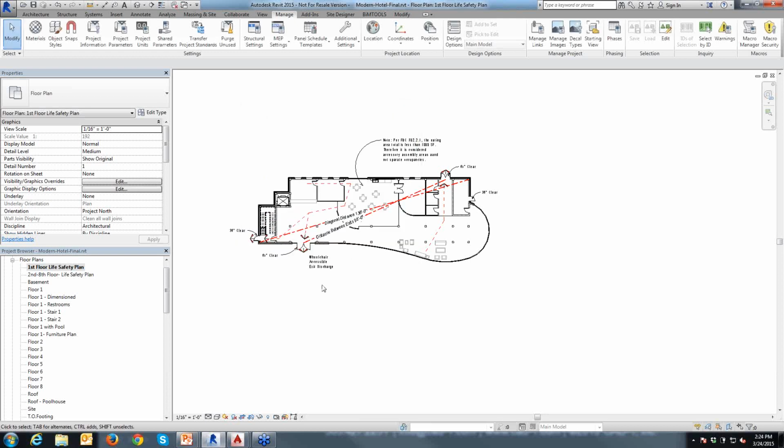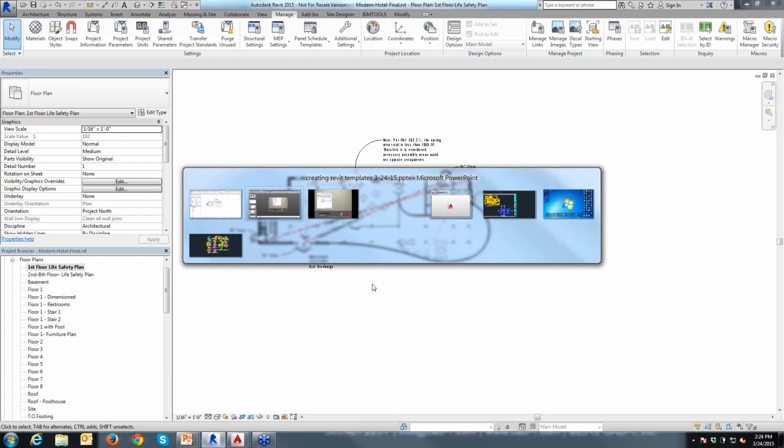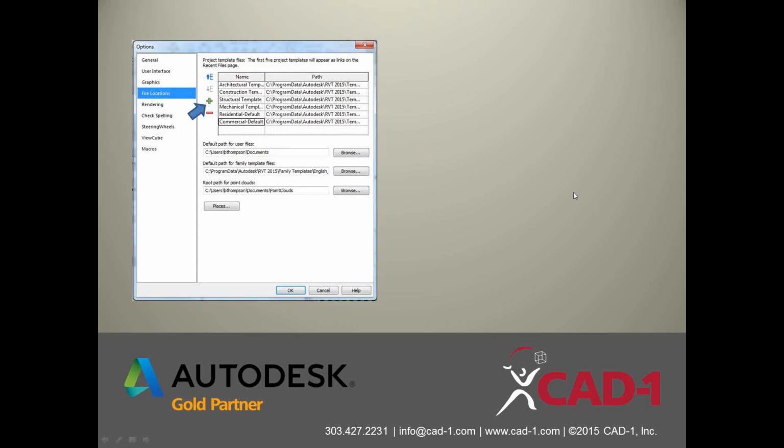We have about 10 minutes left, so I just want to... Yeah. One of the things I will warn you about is transferring over the materials library. You want to really pay attention to the materials library. That's going to be an area that Revit's been updating all the time. But when you're making a new template, I would almost recommend not transferring over the materials library from one to the other. Because what will happen is new assets such as the structural assets, how much materials weigh, and the environmental, or what am I trying to think, the thermal, that's the one. Thermal list, those don't transfer over if they were not created in an older version.